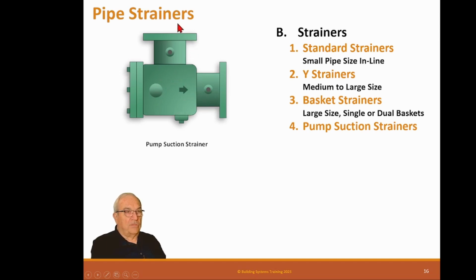What happens is the water comes down, flows into the strainer, and has a sieve, and the sieve catches the debris, and the water goes out. So this is called a suction strainer, and these work fairly well. I'm okay with these. The only problem is when you pipe up a gauge, you need to put it right here or right here, and not up here. The gauge can't go up in the pipe because we can't include this strainer in the pump direction.